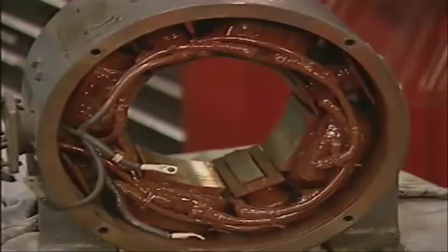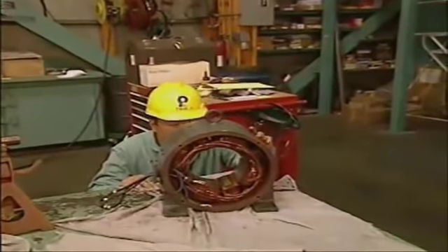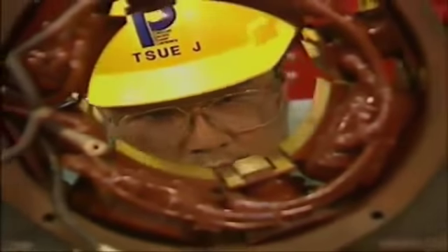The next items to be checked are the motor frame and the field pole pieces. Both of these items are cleaned before they're inspected. Special care should be taken to remove all dirt and carbon dust from the areas between the main poles and around the interpoles. Once they're clean, the field coils and the interpoles are inspected to make sure that they're not damaged. If the insulation has become cracked or broken, it can be repaired with insulation varnish.